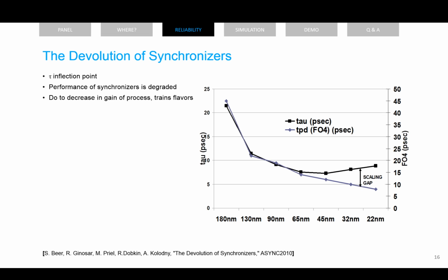So just going on the influence of some of those, one important thing is the technology node. In some research we have done, we have seen that the resolution time constant does not necessarily decrease with the technology node. So relying only on the technology node shrinking for having lower resolution time constants is not completely reliable.